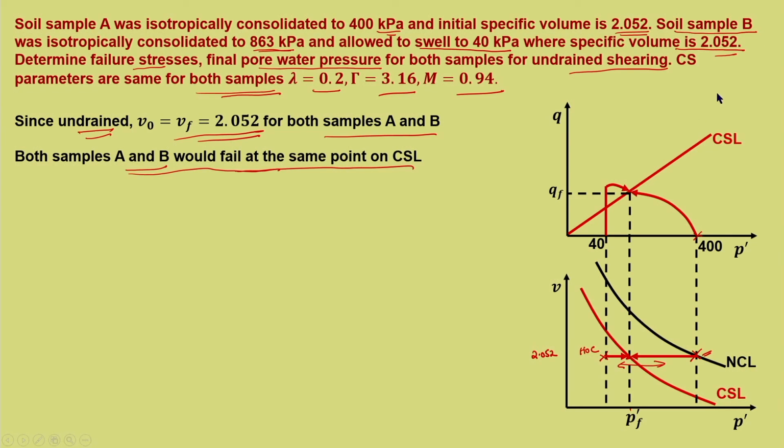With that understanding, and we know that this is an undrained shearing, so A will be equal to 1/3 till it yields. It is all possible and it is in this direction because we know the concept. So, that is the point of yielding. I am not showing the yield curve here separately. Yielding has happened, but it comes and fails at the same point.